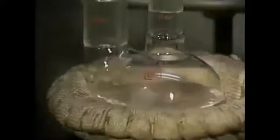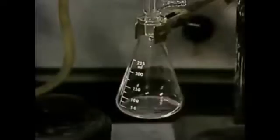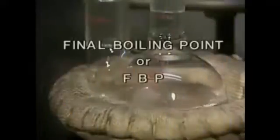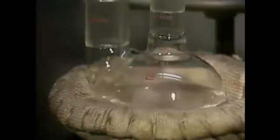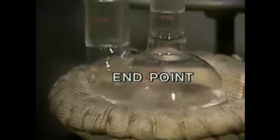First, a substance in a liquid mixture is changed to a vapor. Then, to recover the separated substance, the vapor is changed back to a liquid. The boiling point of the component in the mixture that boils at the lowest temperature is the mixture's initial boiling point, or IBP. The mixture's final boiling point, or FBP, is the temperature at which the component that has the highest boiling point boils. The final boiling point is also commonly referred to as the end point of the mixture. The end point is the end of the mixture's boiling range.